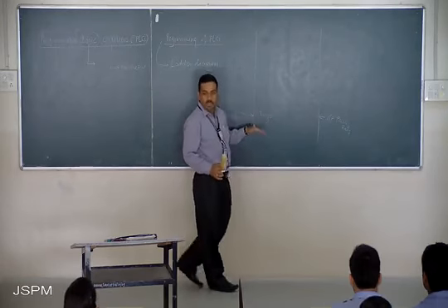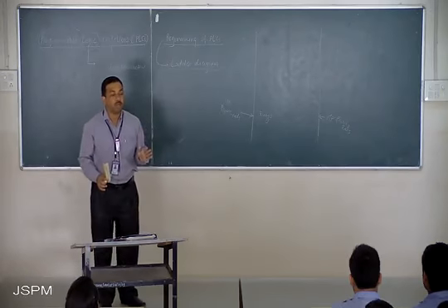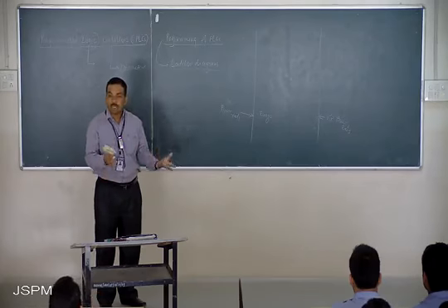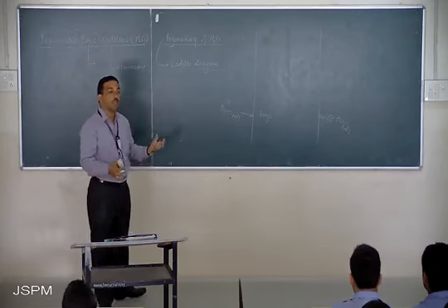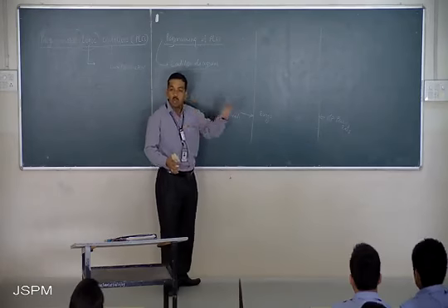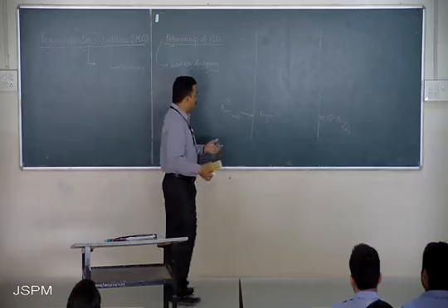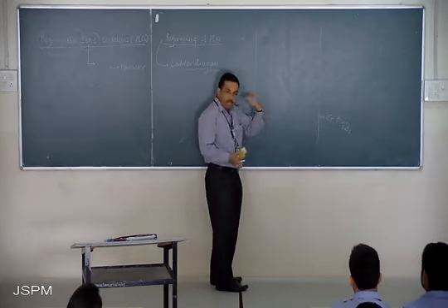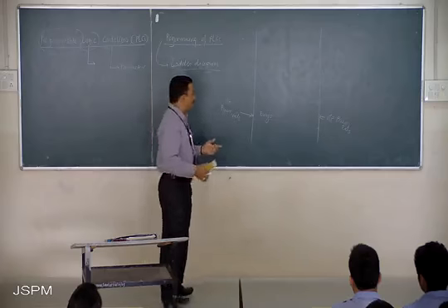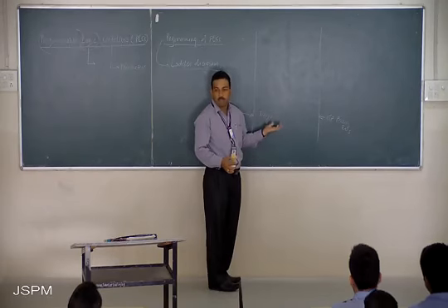can be 5, 10, 100, 200, depending upon the complexity of the system. If thousands of sensors are connected to the PLC, there will be thousands of rungs dealing with the PLC. Are you getting me? Okay. So there is no limitation on the rungs. Depending upon the capacity and specification of the PLC, the rungs can be increased up to 100, 200, 300. That depends upon the logic that you are incorporating.